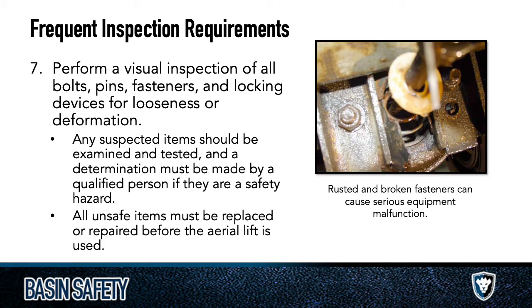We're going to look at bolts, locking devices, or looseness, for deformation, cracks in the frame, especially in the welds, which is typically where we're going to see it first. That gets a little bit more in-depth, but still not a bad idea to check it. All unsafe items must be replaced.